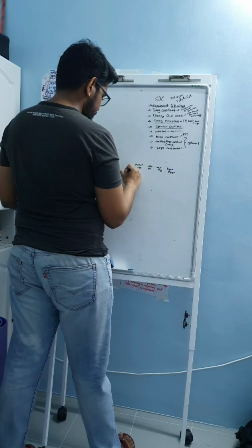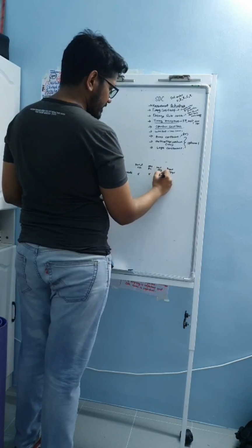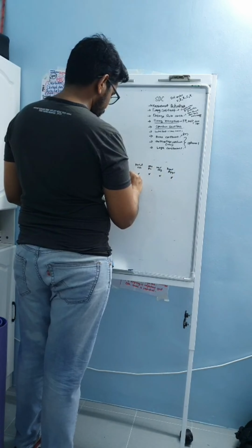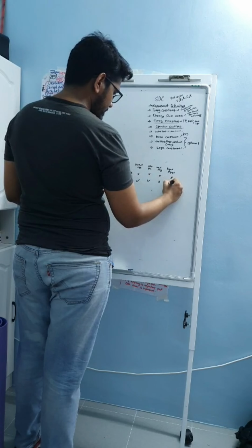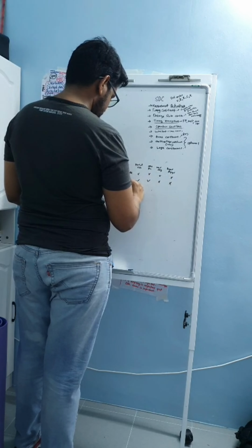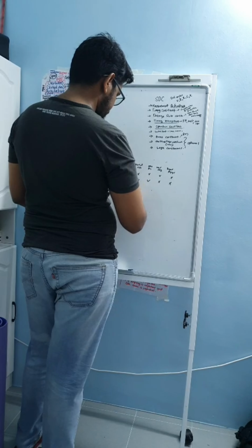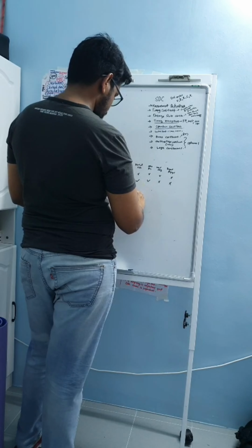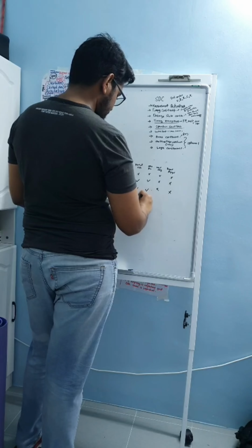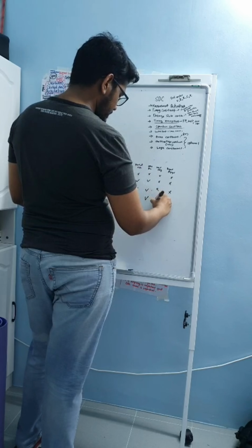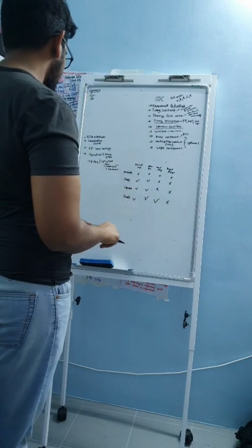So we have exclude. Whenever we talk about exclude, it means everything is X. Whenever we talk about stop, it is part of CTS, it fixes your DRV, but does not insert delay or propagate. Then ignore. Then after that, float. This is part of CTS, you fix DRV, and you insert delay, but it does not propagate.